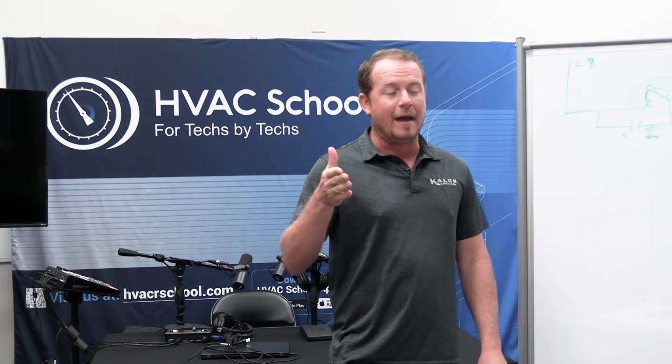Now, if you've got a 50 and you're going to go up to a 55, you know that the capacitors, in a lot of cases out of the box, are a little weak and then weaken over time anyway. So would that be acceptable? Use your judgment in those cases, because as a percentage, that's not a significant increase. But this is where a lot of people say, well, the thing's rated for a 5, but I'm going to put in a 7.5 because that's all I've got. Well, as a percentage, that's a huge percentage increase. The percentage difference between a 50 and a 55 is a very small percentage increase. Don't use a 7.5 to replace a 5. Don't use a 10 to replace a 7.5.